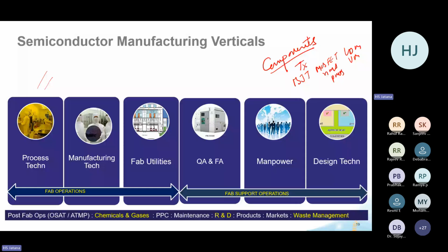Then within NMOS, by voltage, we have a 1.8 volt device, a 3 volt device, a 5 volt device, like this. Now within the 1.8 volt device also, we have devices with a normal threshold voltage, which we call VT normal, high VT, VTH, and low VT, VTL. So there are 3. And then there are devices which we call native transistors within 1.8 volt itself. So there is a wide range of devices available, and the design of each device is different.